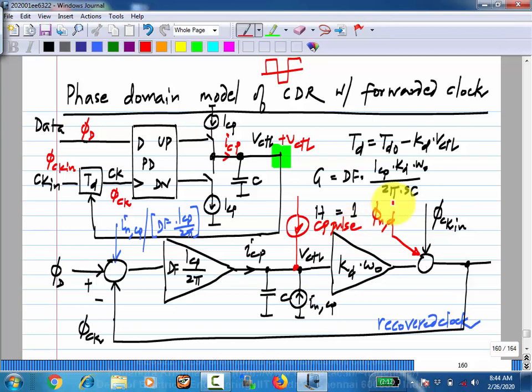So this is in general true of every phase detector. The average output of the phase detector follows the phase difference, but in addition to that, there will be some periodic error, some jumping of signal back and forth. So now this also causes a similar periodic error, some changes in the output phase. This is not so important with the linear phase detector, but with other kinds of phase detectors it will become important, as we will see in the Bang-Bang phase detector and so on.